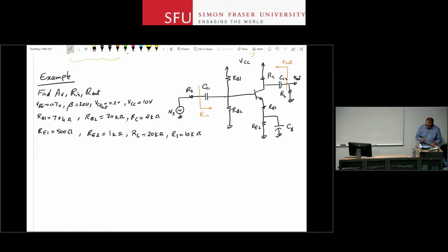Now, for this circuit, the first thing we need to do is to do the DC analysis. You notice that there are three capacitors here. CC, these are the coupling capacitors, and we talked about the role that they have, that they separate stages at DC from each other. So they let you focus on the DC analysis of one stage at a time. But you also have this CB capacitor here. And when you're analyzing these circuits, we assume all of them are short-circuited at AC frequencies, okay?